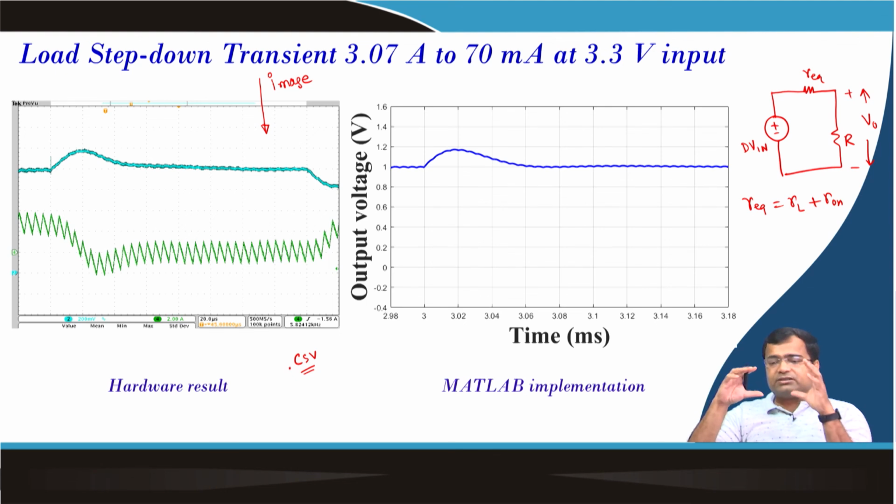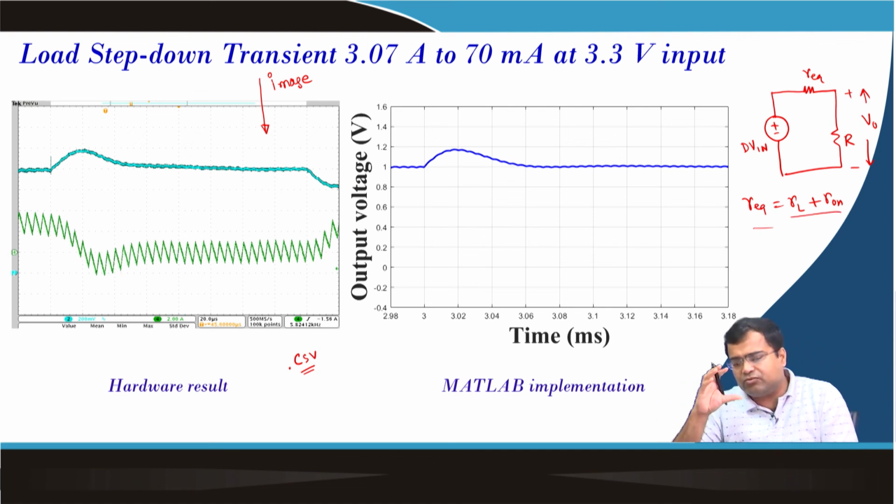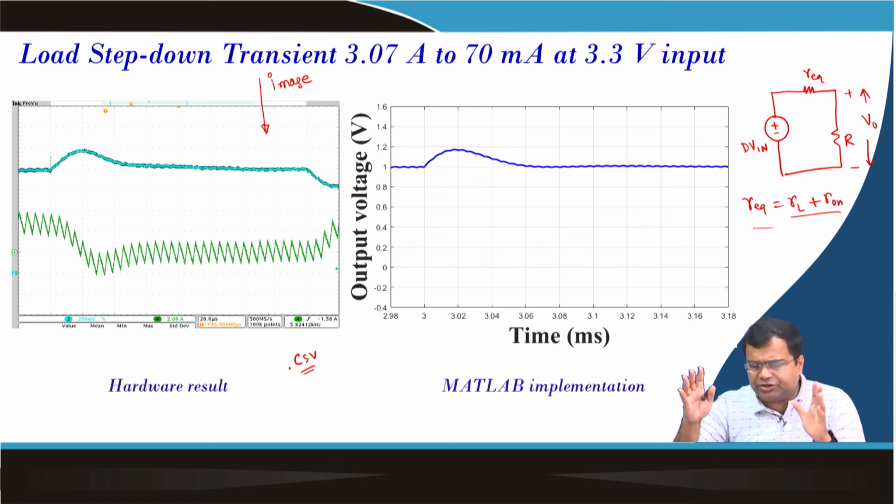If we consider synchronous buck, and if we consider the on state resistance of the high side and low side MOSFET are same, then you can represent. So, getting these values are very difficult, and we have used some procedure to do checking by running some DC equivalent case study, and we got some reasonable value for this.